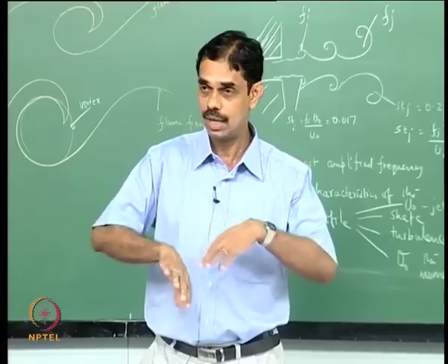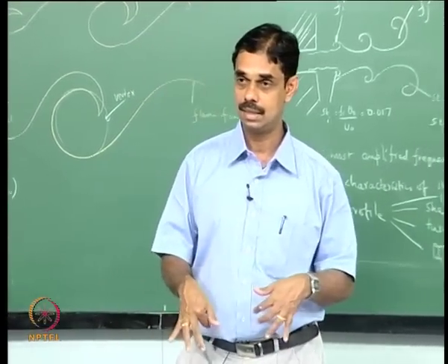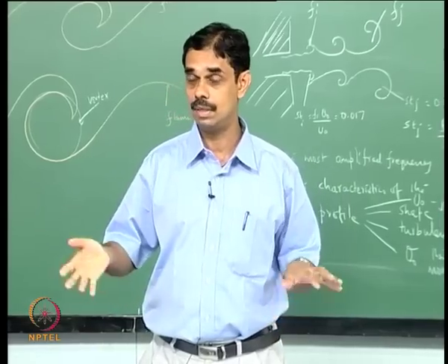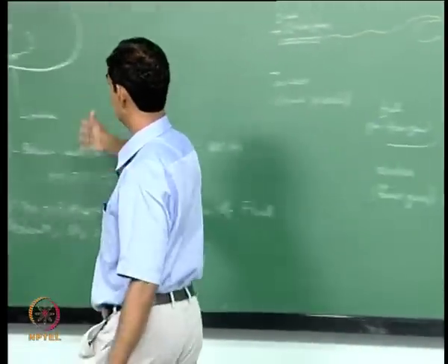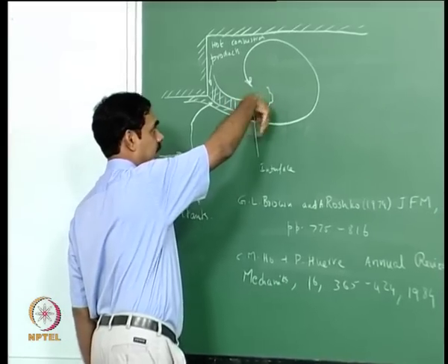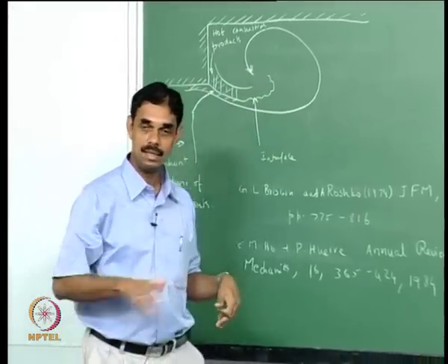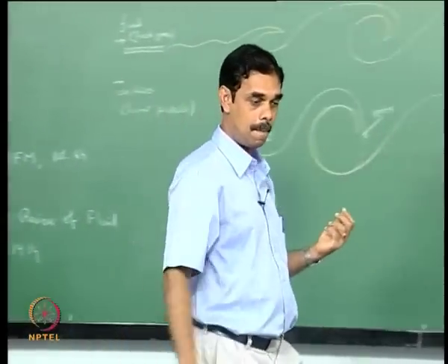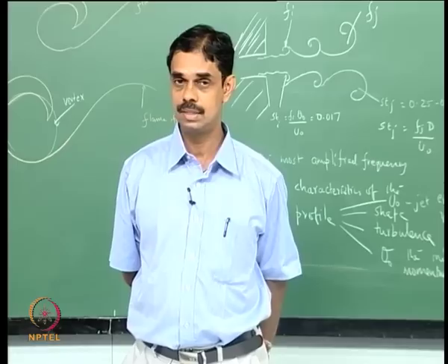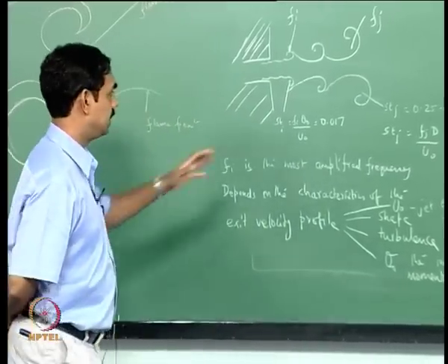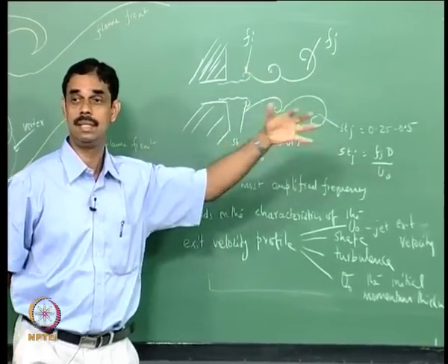And once you have the coherent structure, it leads to this bulk mixing, and then if the high strain rate is available, which happens during roll up, then you can have this fine scale mixing and combustion. So that is why it does not really start burning right from the beginning, it just gets in, and then it rolls up, and then it bang, it burns, and then again the same thing happens. So it happens in a periodic way. People have taken high speed movies and have seen this. So does it answer your question? It is about this guy responding to certain preferred frequencies, so if you excite at those preferred frequencies he will respond.